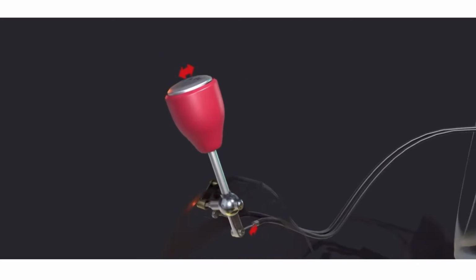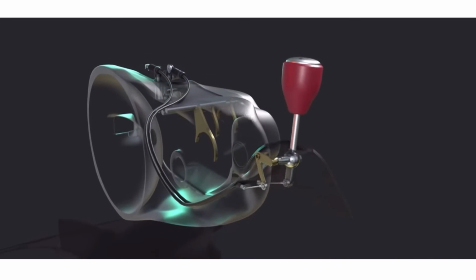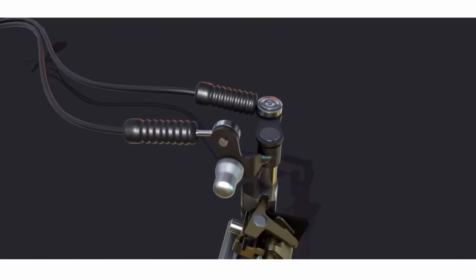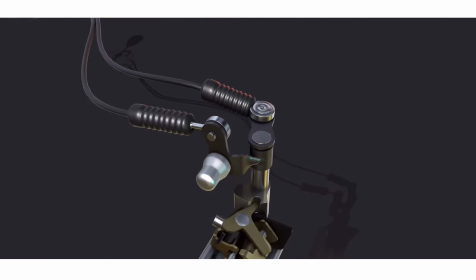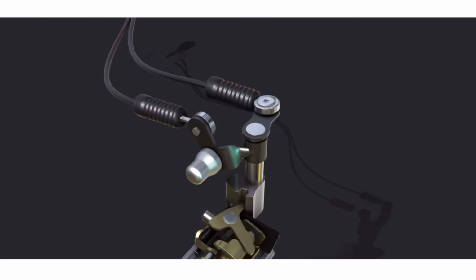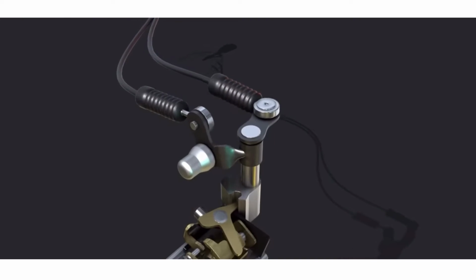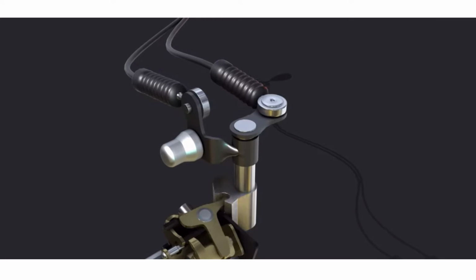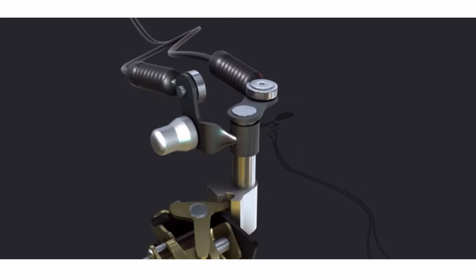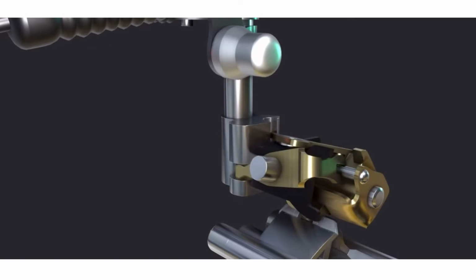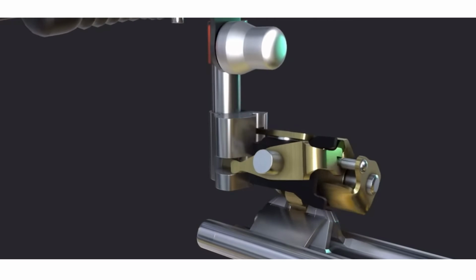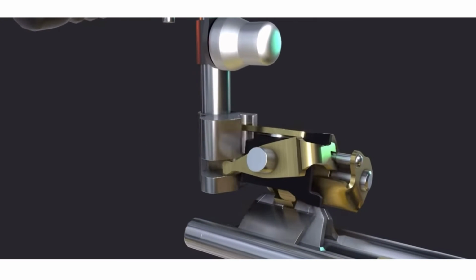When the gear lever is pushed or pulled by the driver in order to select the particular gear, the synchromesh device, which is attached to the particular link, slides towards the selected constantly meshed pair of gears. At first, this synchromesh device makes frictional contact with the selected pair and the shafts in order to bring the rotating shafts to the same speed. Then the pair of gears having an appropriate gear ratio meshes with the synchromesh device in order to obtain the output given by the pair of gears, which is then transferred to the main shaft.